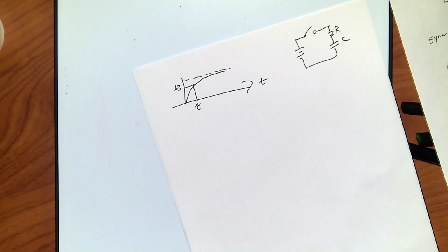Actually, if you think about it, an awful lot of our systems latch below 1 volt and latch above 4 volts on a 5-volt scale. So technically that's 20-80, right? But you're going to have some number of these that's going to matter. How strong does it have to get? That's going to depend on your system. Sometimes we try to critically damp, we could do all kinds of things. We could try to get it faster by doing overshoot, but then you get oscillations and settling time. So there's a lot of ways we can try to speed this up.